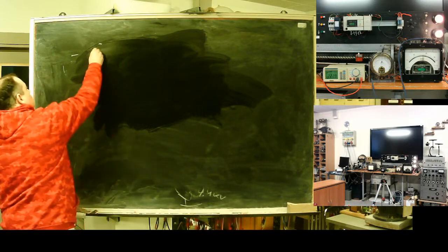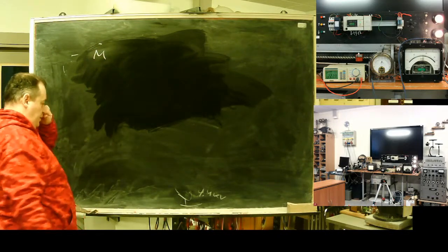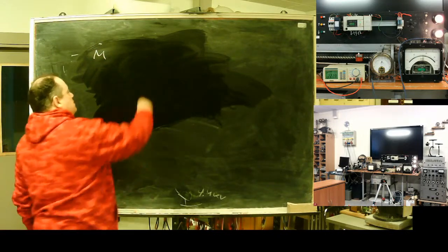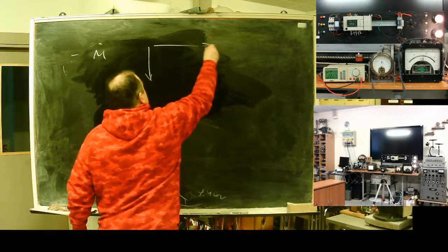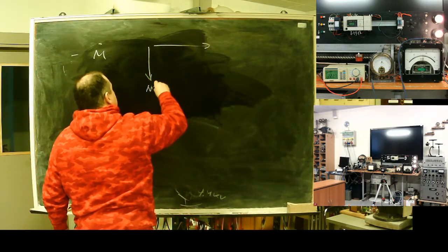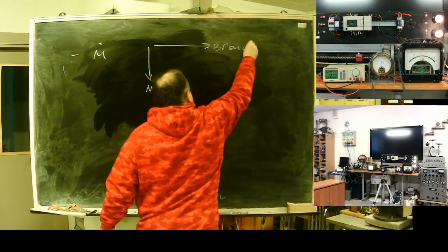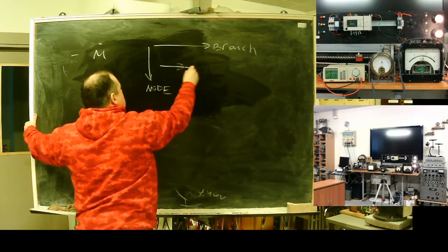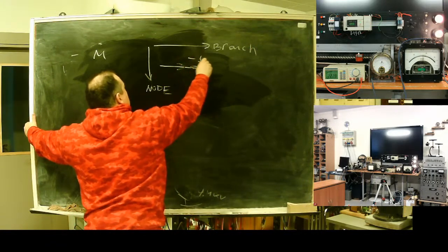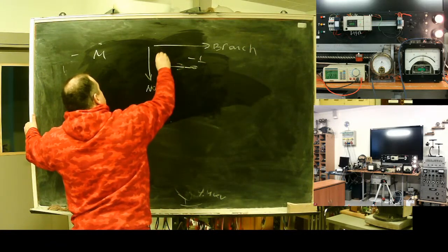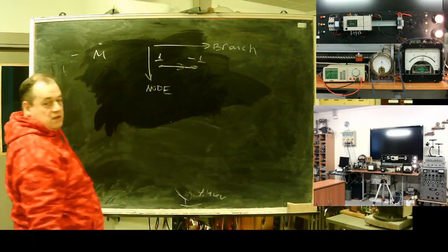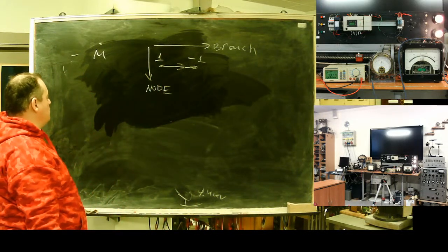Network topology is defined with the M matrix. If a branch falls in a node, we write -1, if it falls from the node, we write 1, with no connection we write 0.